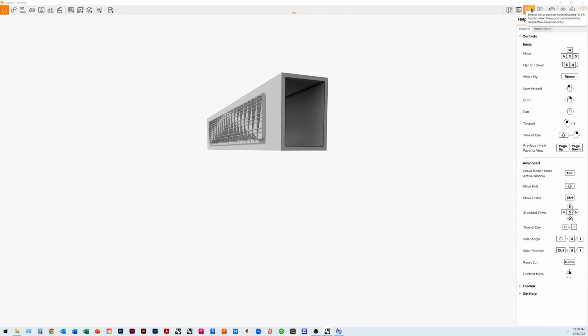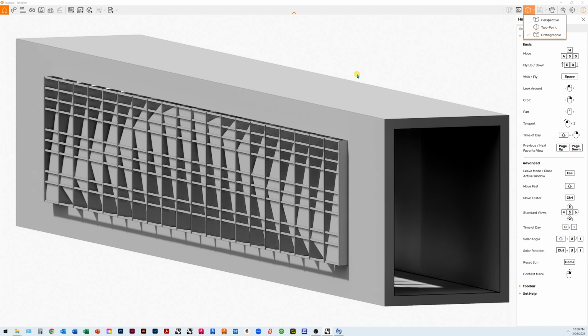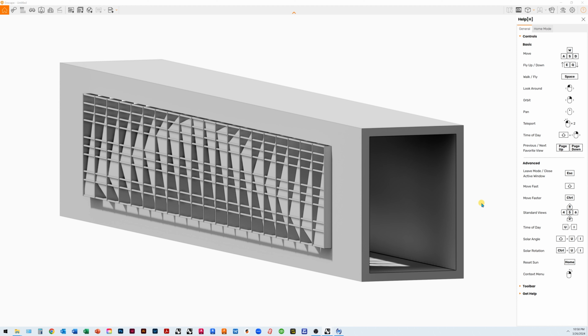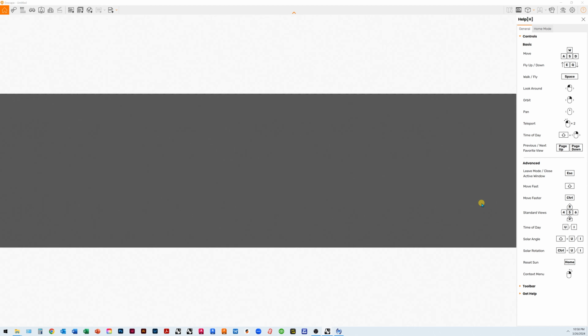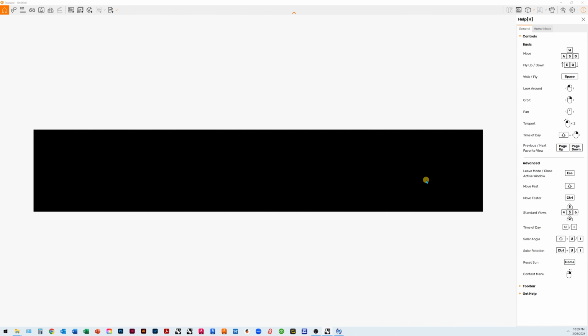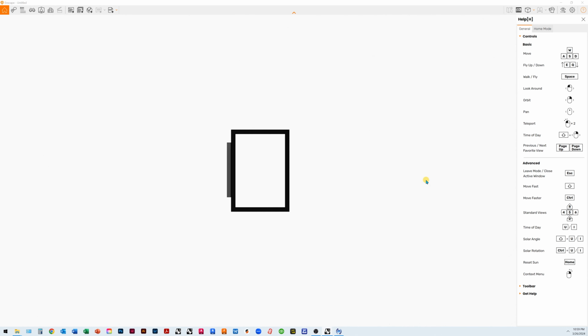And then we talked about these setups for different orthographic views. Now, once you're in orthographic and you're clicked on here, you can see up on the right hand side you get a couple different views, standard views. So let's look at what happens when we use those. If we click into the space and then we use, I like to use the number pad. If we do 8, it starts to give us all the flat views of our project.